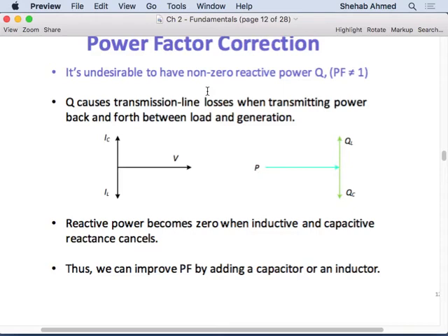Immediately, right? So the capacitor current changes immediately. So it's a huge inrush current, very large currents. On a distribution network, very large currents cause voltage drops. Because again, distribution networks are not like transmission networks. In a transmission network, we have big transmission cables, big diameter, low resistance. Distribution networks have smaller diameters, so larger resistances. Larger resistances mean if you pull a lot of current in a short period of time, you get significant voltage drops, which can affect other equipment, right?